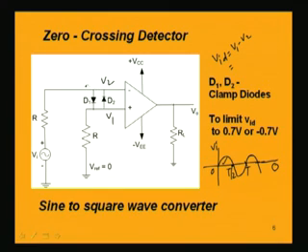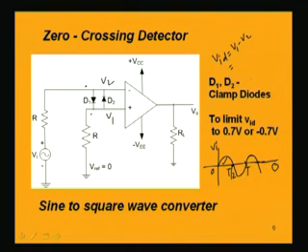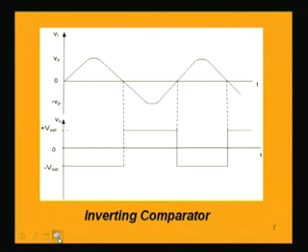This is 0.7 here, positive and negative, but as the difference voltage is V1 minus V2, it will be minus 0.7. So, minus 0.7 into the gain A, but that will be limited to the saturation voltage around 14 volt, but negative saturation. So, we will get a negative voltage when Vi is higher than V reference, means in the positive half cycle. So, in the positive half cycle of the input voltage, we get negative Vsat. That means it is an inverting comparator actually.